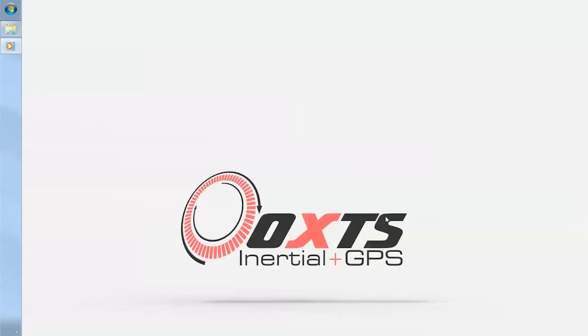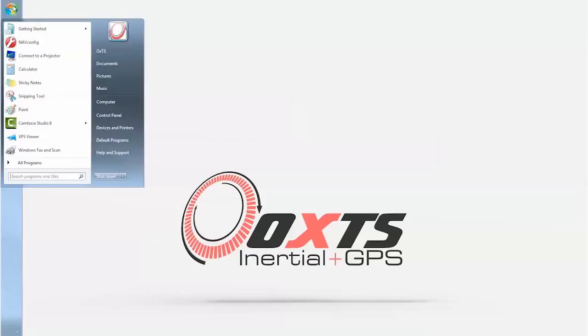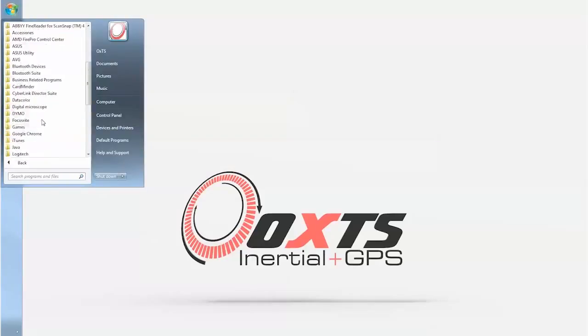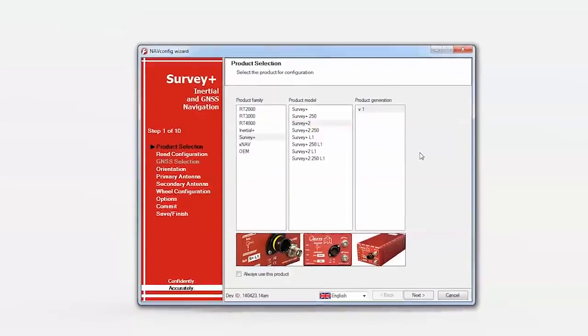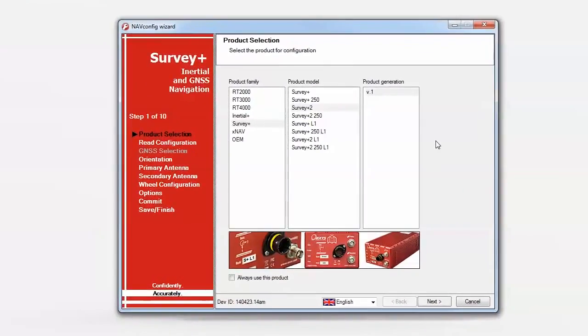Once the software supplied with your product has been installed, NAVconfig can be started by clicking on the Start menu, then All Programs, and scrolling down to the OXTS folder where you will see the program's icon. Although an Ethernet connection is required in order to send a configuration to your product, NAVconfig is actually an offline editor. That means you can create and modify configurations without having a live product connected.